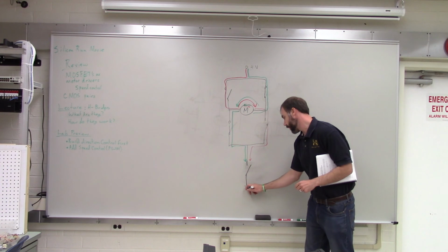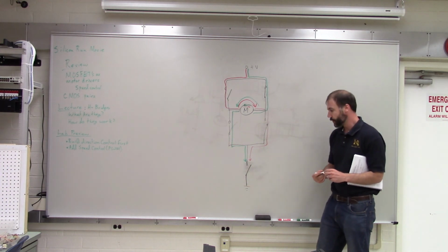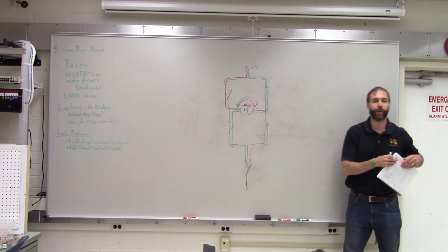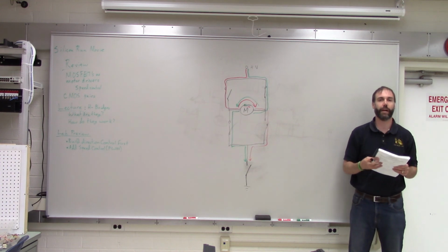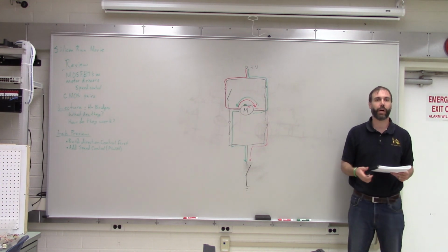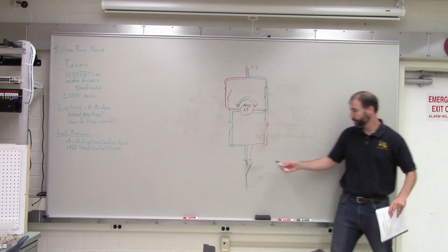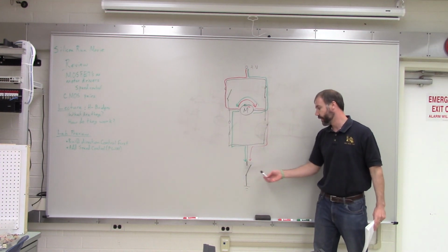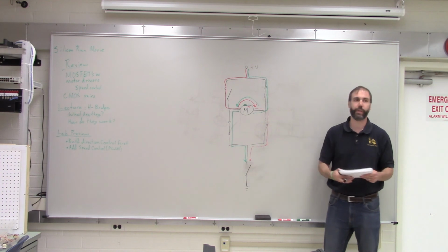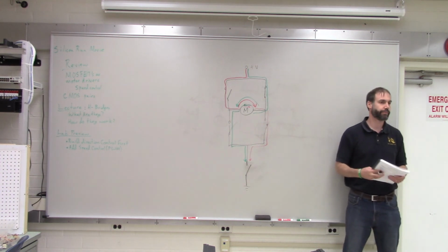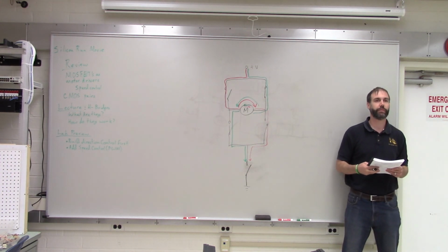And then you're going to control that transistor with the square wave output from your function generator, just like you did last time. You're going to pull that duty cycle knob out again and vary the duty cycle so that you can control this with PWM and control the speed of the motor. So, any questions about that?